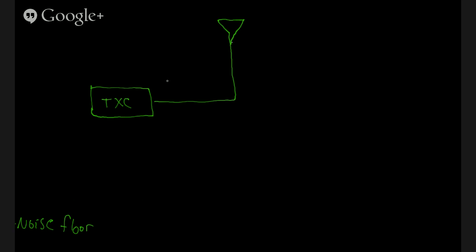Since an antenna is a type of load, we need to make sure that the impedance output of the transceiver matches that of the antenna system and feed line. If they do match, all of the power coming from the radio going into the antenna gets radiated, so all the power is transferred with minimal losses.